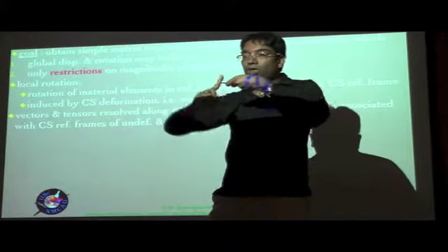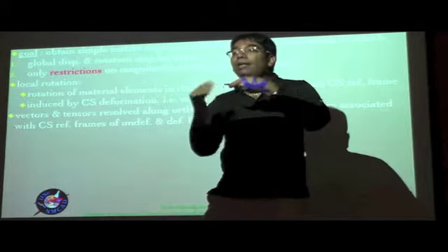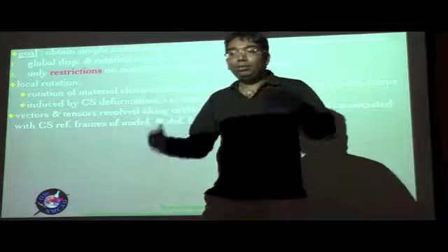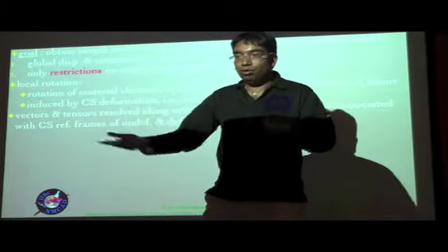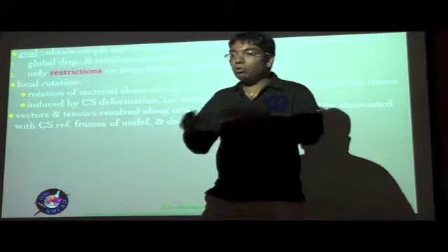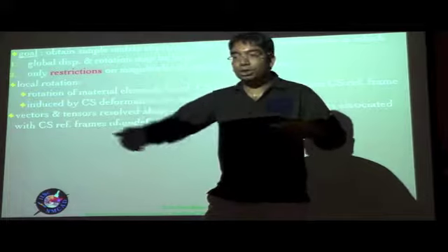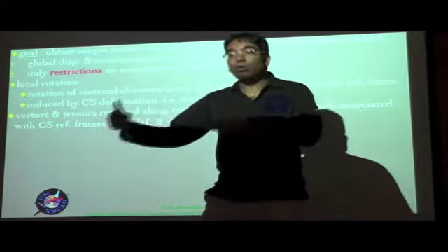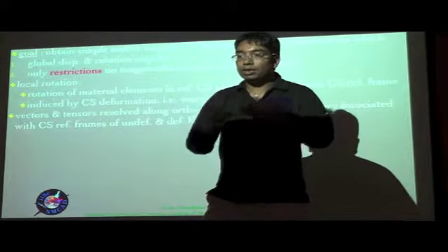So basically it's a rotation like this of the line element, right? That local rotation, if it is very large, will make the strain gamma 1,3 very large, which would make the material fail, and therefore the beam would not be able to hold the load. So what we are dealing with is a healthy beam, and therefore you have a restriction on W1,3 and therefore on the local rotation. Similarly, you can extend that idea to the other local rotations as well.